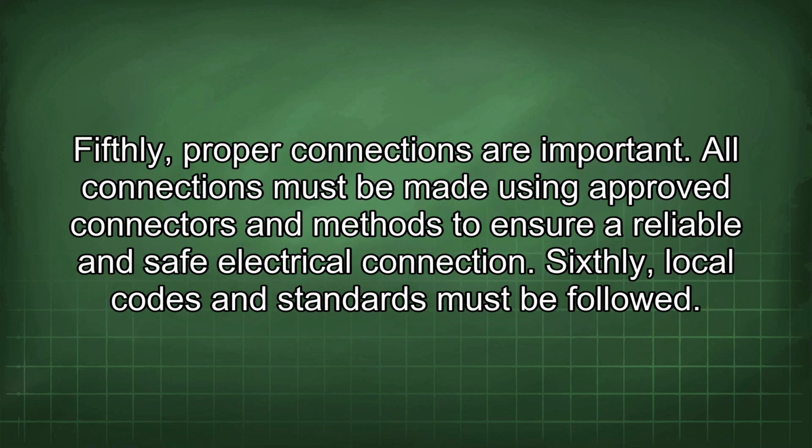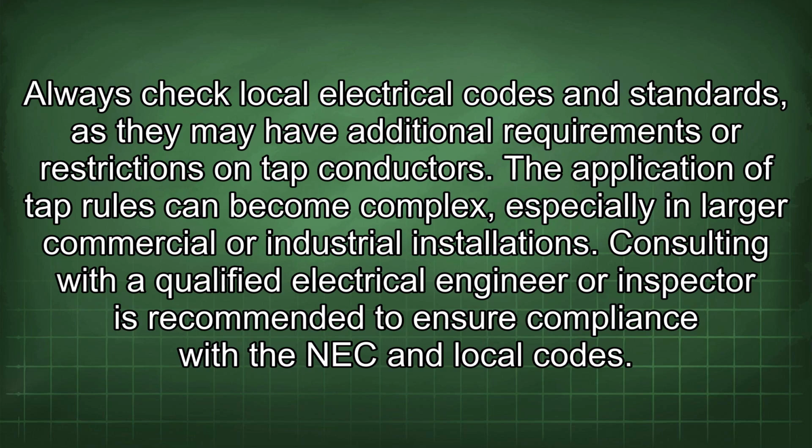Fifthly, proper connections are important. All connections must be made using approved connectors and methods to ensure a reliable and safe electrical connection. Sixthly, local codes and standards must be followed. Always check local electrical codes and standards, as they may have additional requirements or restrictions on tap conductors. The application of tap rules can become complex, especially in larger commercial or industrial installations. Consulting with a qualified electrical engineer or inspector is recommended to ensure compliance with the NEC and local codes.